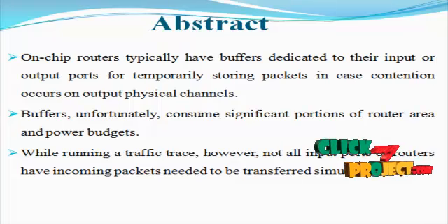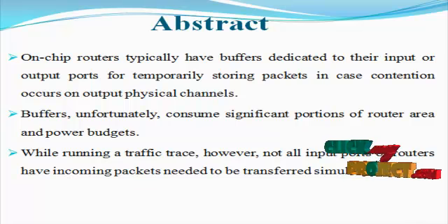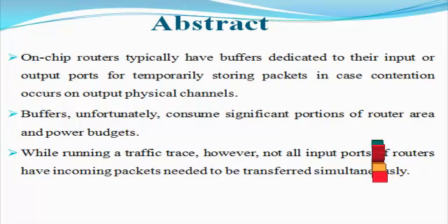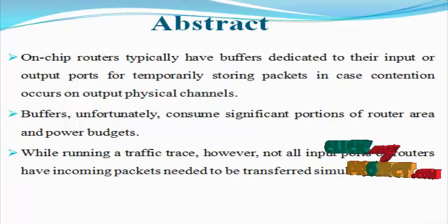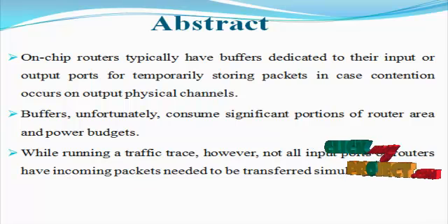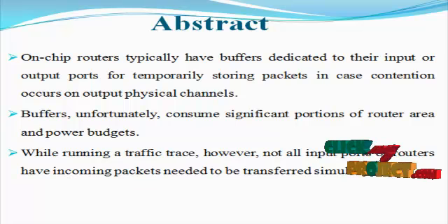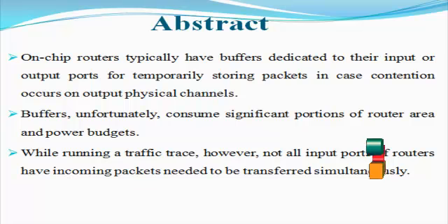Next we see the abstract for the project. System on a chip is moving toward multi-core design for taking advantage of technology scaling and also for speeding up system performance through increased parallelism, in the face of power wall limits to increasing the clock frequency. Networks on chip are shown to be feasible and easy to scale for supporting a large number of processing elements, rather than point-to-point interconnect wires or shared buses.